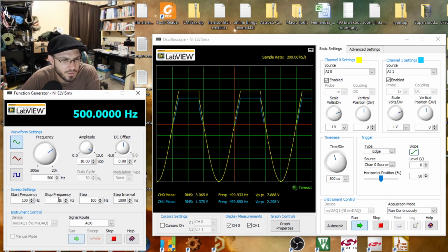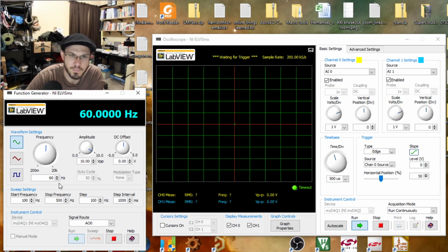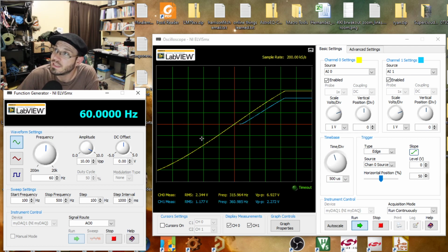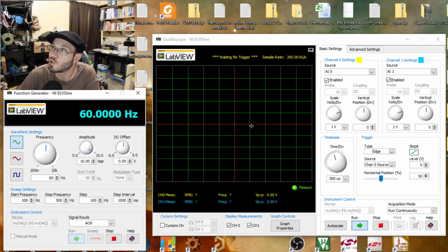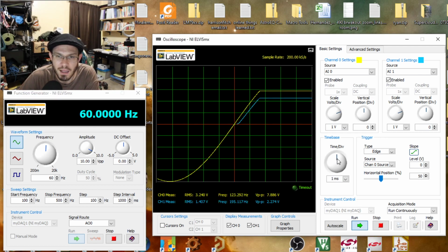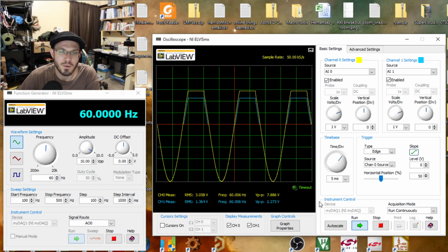Okay, and let me try dropping the frequency. That looks like that made it worse. Let's go from 500 hertz, let's take this to 60 hertz. And if you notice when I lowered the frequency, now it's not able to show an entire cycle on the oscilloscope. And in fact, it's having a hard time even triggering on it because of how slow it's going. Let me change that time base. There we go. Okay. And we are still seeing that clipping.